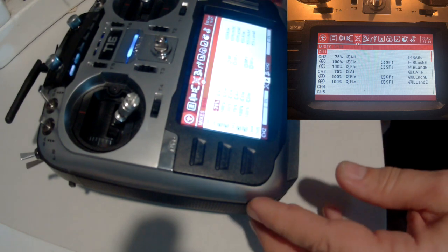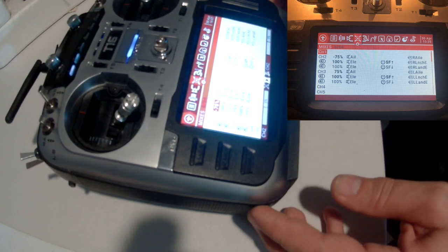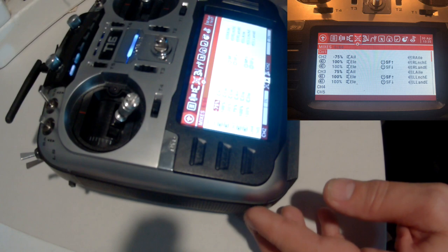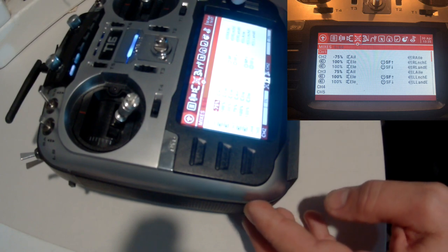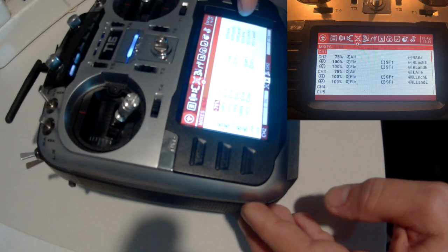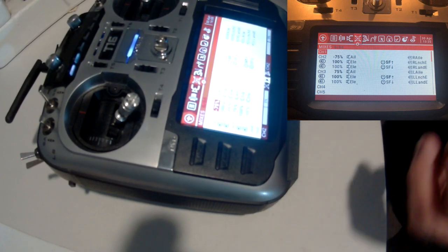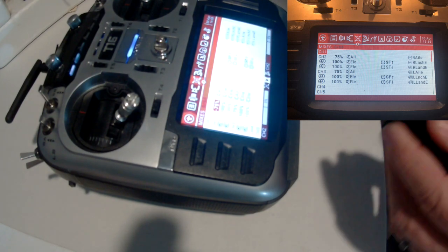So you can see over on the right hand side, I've called the switch down, which is the up arrow, is the launch mode for the right servo, and then the elevator will go into landing mode when the switch is toggled to the up position.